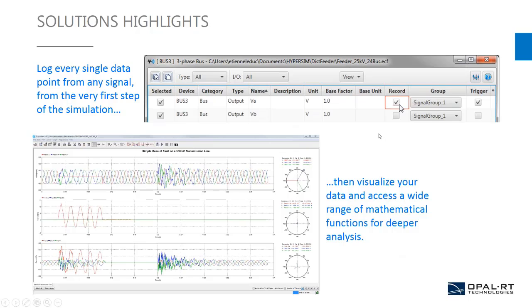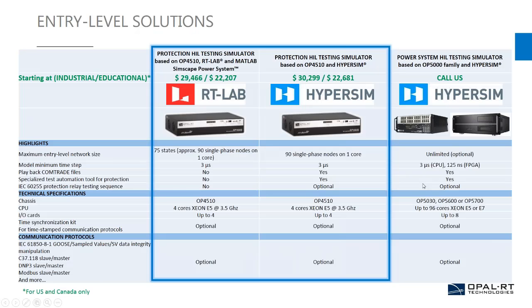Another very important feature is the data logging. So you can log every single data point from any signal from the very first step of the simulation simply through a simple click, selecting the signal of interest, and then visualize your data and access a wide range of mathematical functions for deeper analysis in scope view.